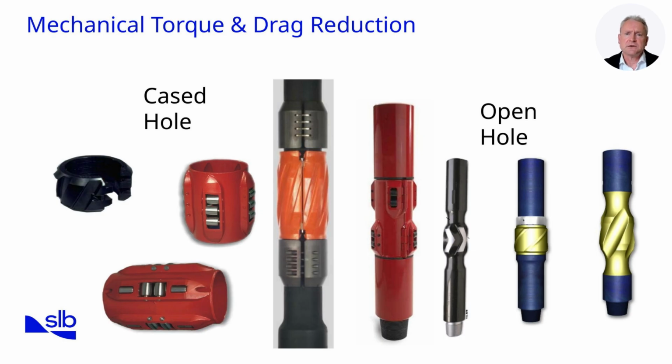This increases the hydraulic pressure required, which may reduce the flow rate due to pressure restrictions. Also, the rubber elements can be damaged and fall off, causing a fishing problem and a potential stuck pipe issue. Rotating protectors/subs. These rotate with the drill string, reducing torque by lowering friction against the casing. They are placed in high contact areas where side forces are greatest.